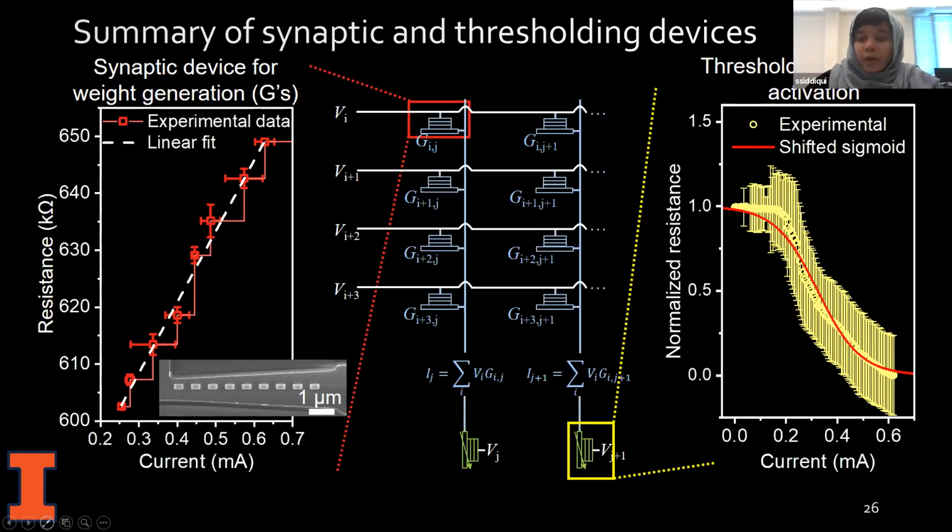That's a great idea. One drawback is that whenever you want to vary the duration of your pulse, that comes with the requirement of external circuitry, because you now want not a single clock signal but multiple different duty cycles of those clock signals. So it's probably some amount of compromise, what works best in terms of energy and processing time. But the magnitude of the current is also possibly okay within some reasonable ranges, right? Sure, I'm not worried about the magnitude of the current. I'm worried about the extra circuitry needed to generate these variable width pulses. You also need to look into all the filter weights, what amount of change you have, which direction you want to go, and calculate what pulse width you have to apply.